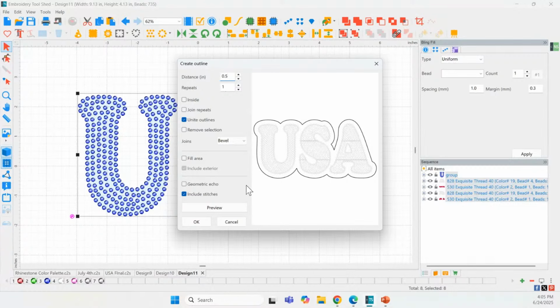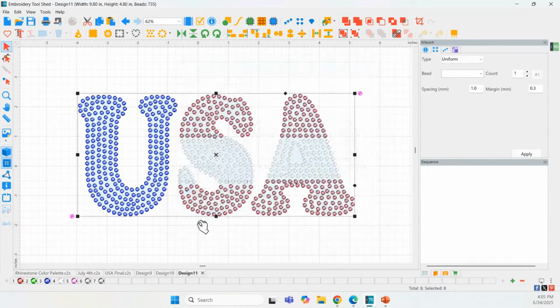And a 5. If that doesn't do it, we're going to manually work on it. Okay, that doesn't do it. So let's manually work on it. So I'm actually going to go back to like a 0.4 preview and make it round, just makes it smooth. Okay. And then click OK.